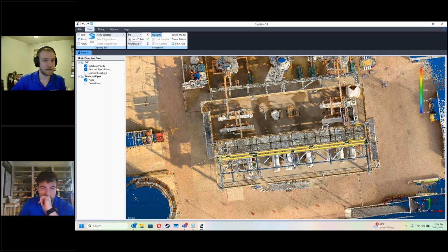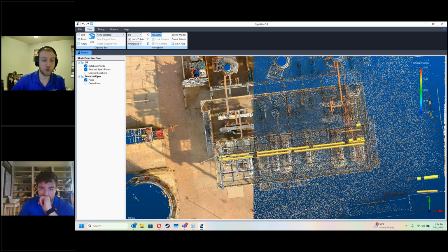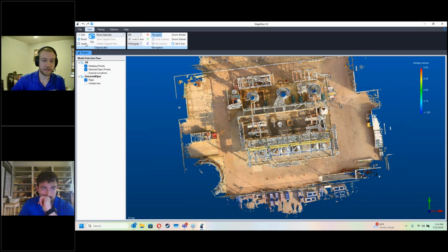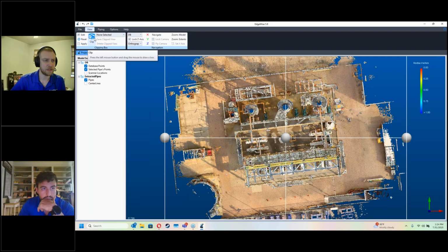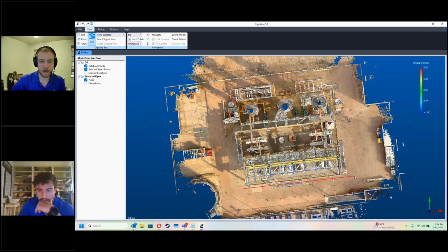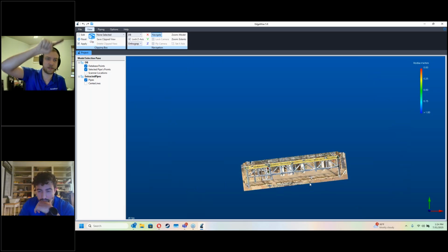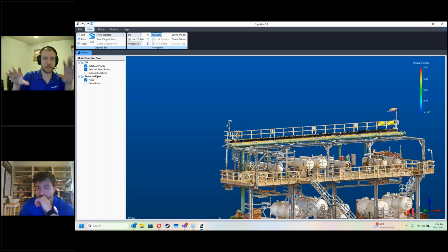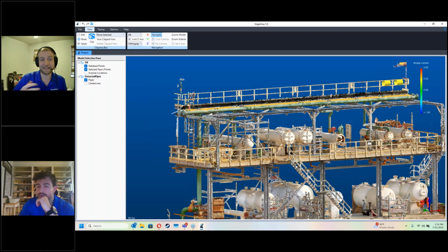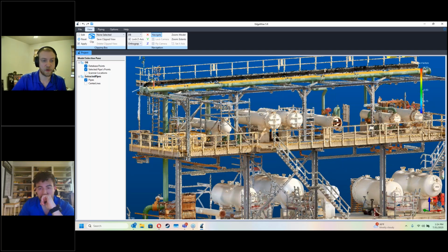Using the clip function, you can click first on, say, a corner, so if you want a top-down of that section, you can see how Trevor is able to rotate that angle. That first click gives you your starting point. The second click lets you set the x-axis and y-axis rotation and then expand it from there. That's a really quick way of setting your options.